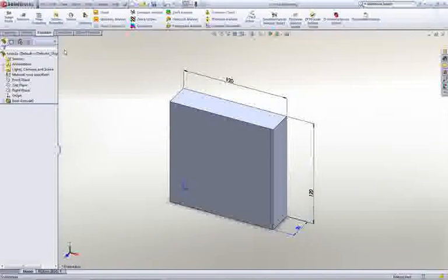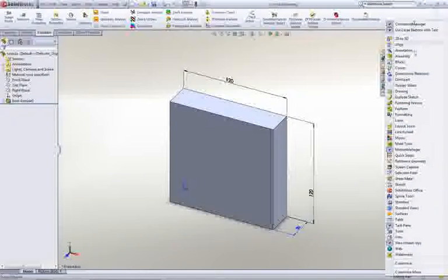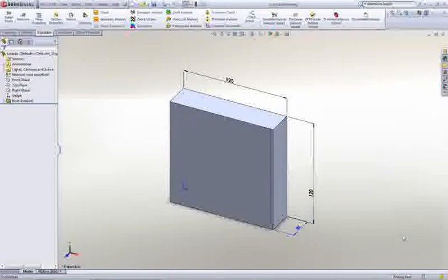By default, SolidWorks has many toolbars open, such as the task pane. Depending on what you're using SolidWorks to model, you may need quick access to different toolbars. To view or hide certain toolbars, right-click anywhere on the Command Manager and select the toolbars you want to make visible. You can also drag the toolbar to customize its location.